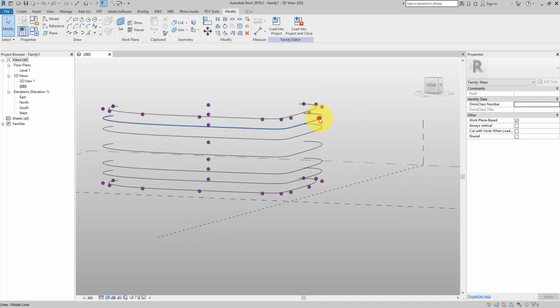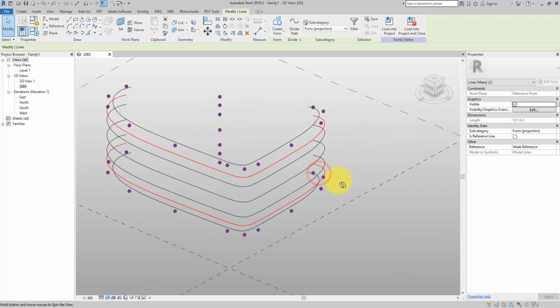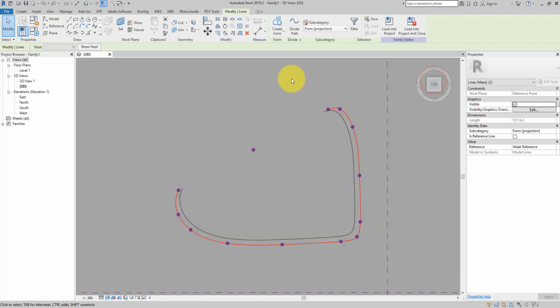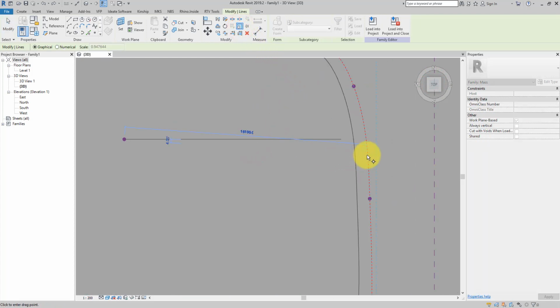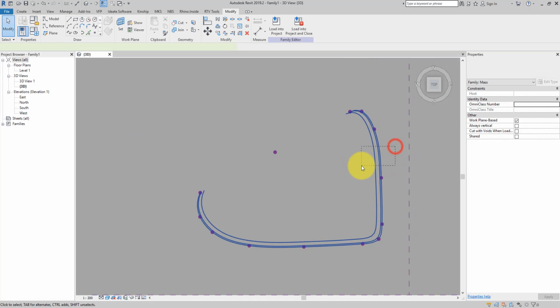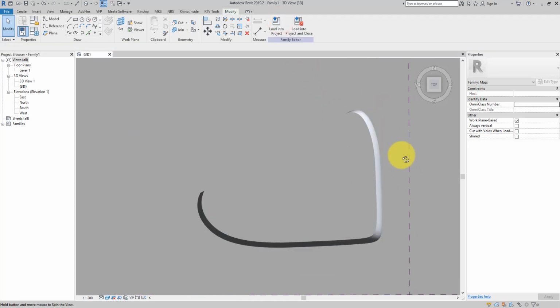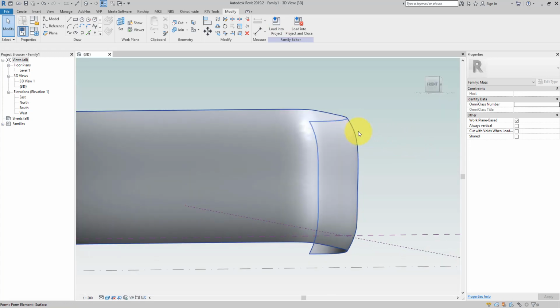Next step, we can select this second line, and this other one second from the bottom. We go to the top view again, and redo the scale command. This time, I'm going to scale these two by just a smaller amount than I used on the previous two lines. So maybe to somewhere there, in the middle. Like this. Get those lines, create form again, and see if that's better. It is, because I have here a smaller curvature, so this middle segment is not so bumpy.